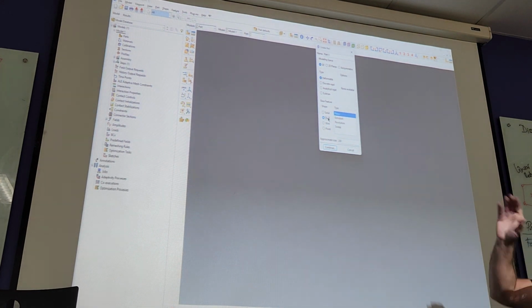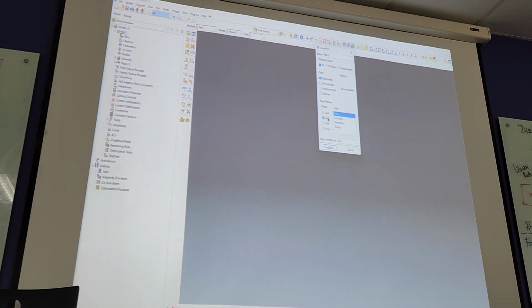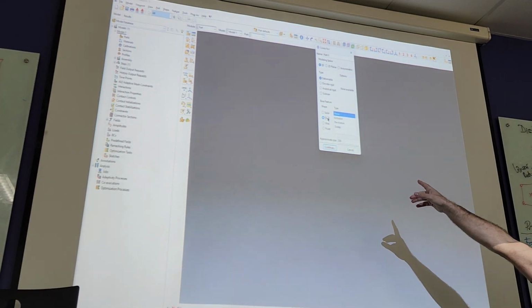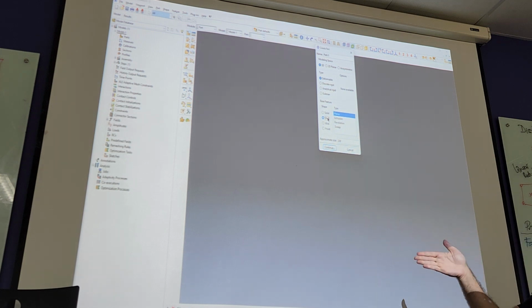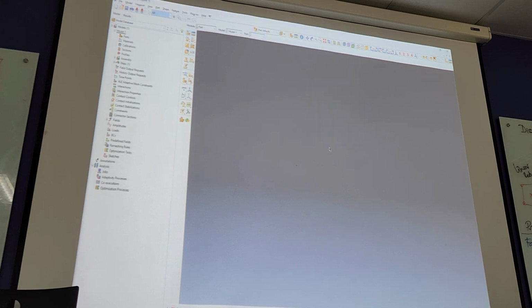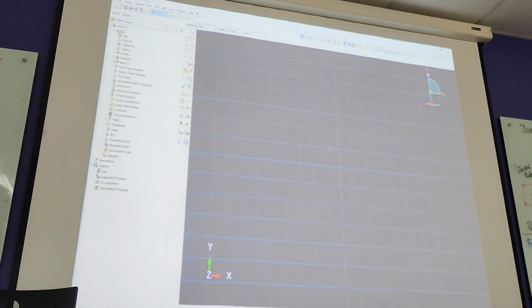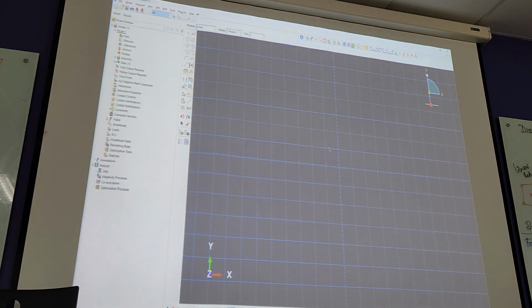Now, how are we going to model this? Planar means whatever I sketch, thickness gets sort of attached to it. So basically I'm doing a planar view. Extrusion is if I do lines, those lines will be extruded into a plane. And revolution and so on. So extrusion makes sense to me, yeah? Because I'm modeling this blue. So basically I'm modeling those 1, 2, 3, 4, 5 lines, which I'll extrude in this direction. I'll have a surface.